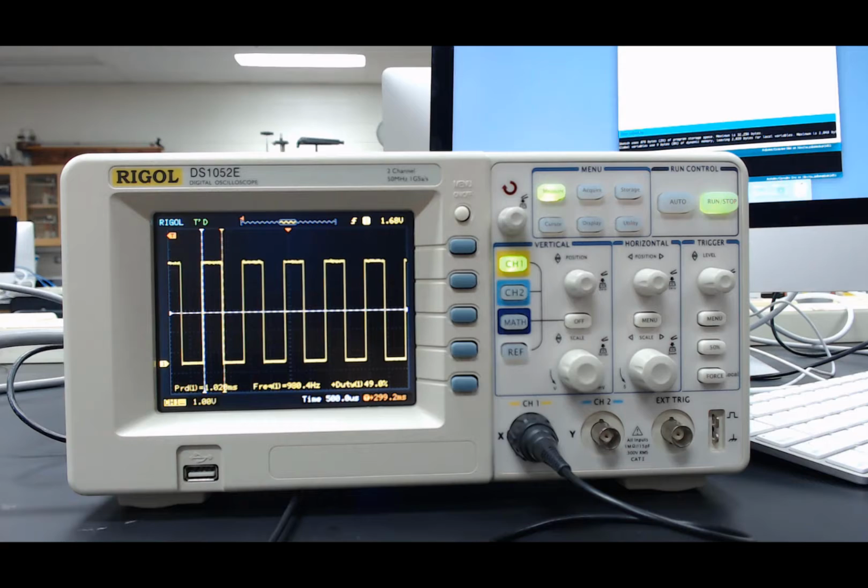So it turns out that most of the digital input-output pins on the Arduino Uno that can do pulse width modulation are going to generate a pulse width modulated signal that's 490 Hertz. But there's two pins, digital pin 5 and 6, which generate pulse width modulated signals at 980 Hertz instead of 490 Hertz. So why is that so? Well, these signals are generated on board using peripheral devices called timers, and the timers that are being used to generate the pulse width modulated signals on pin 5 and 6 are different.